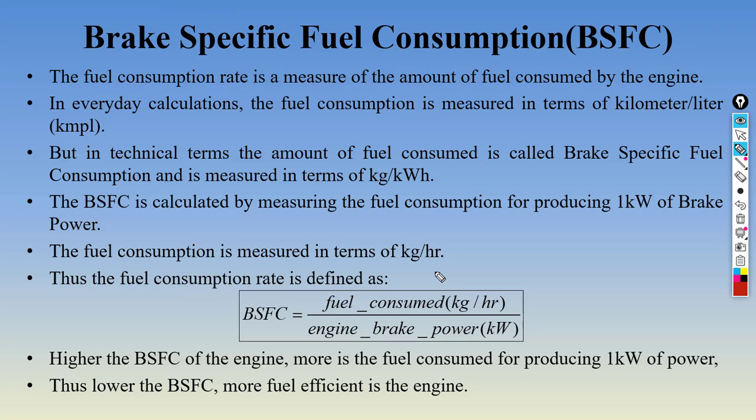What is the formula of BSFC? It is mass flow rate of fuel divided by brake power. And mass flow rate of fuel should be in what? Kg per hour. And brake power should be in what? Should be in kilowatt. Okay.